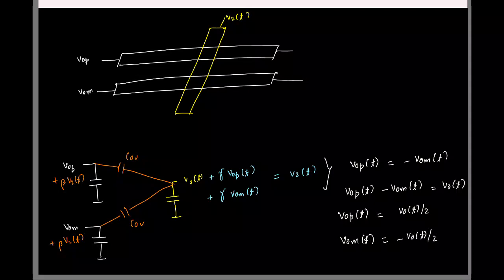If you make sure they are exact negatives of each other, we will not have any interference caused onto any other line, right? And this is how we usually choose also. And in practice, most of the times you don't have negative supplies, so we add some DC voltage to it. I'll call it some output common mode VOC.